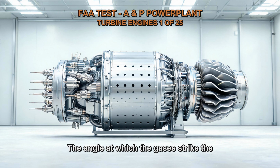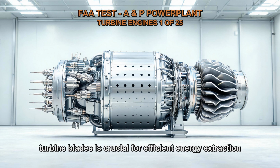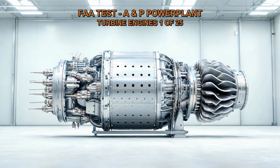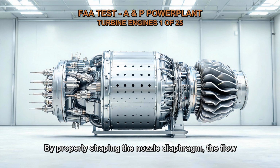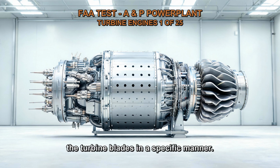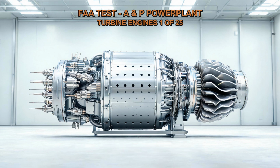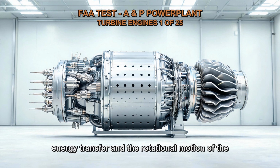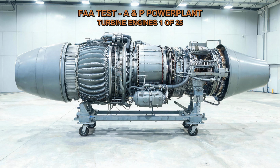The angle at which the gases strike the turbine blades is crucial for efficient energy extraction and optimal turbine performance. By properly shaping the nozzle diaphragm, the flow of gases can be directed and channeled towards the turbine blades in a specific manner. This helps ensure that the gases hit the blades at the correct angle, which maximizes the energy transfer and the rotational motion of the turbine.